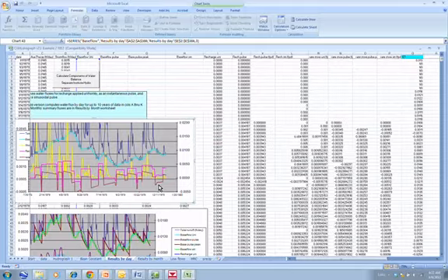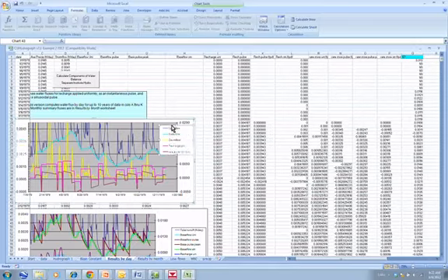We use this base flow separation technique that we just saw, and we also use an interpolation technique between the turning points that's based on the assumption in this case that the recharge between the turning points is uniform. And we also then have the recharge. This pink line here, we expand this out here. This gives us the legend here. There's the recharge.